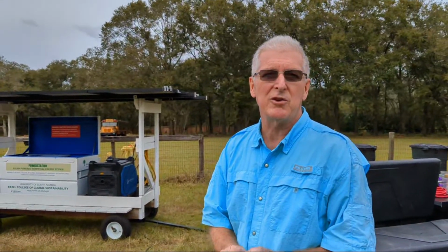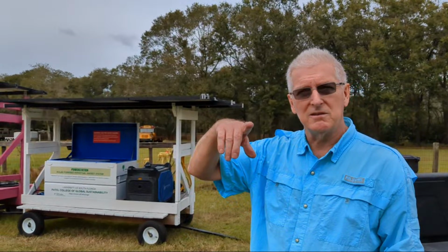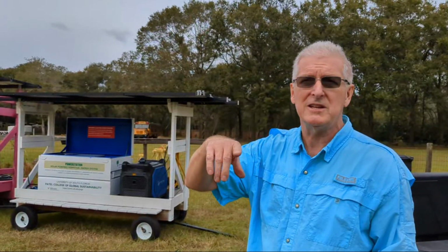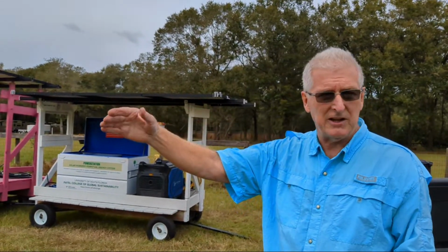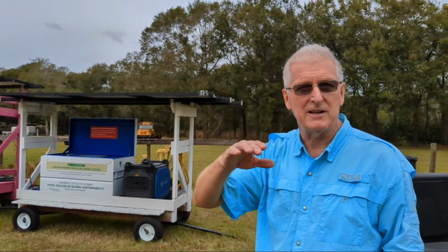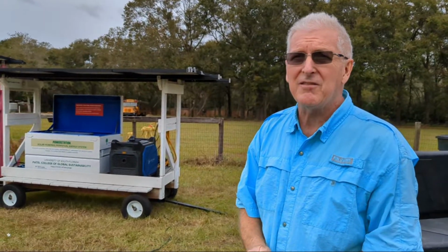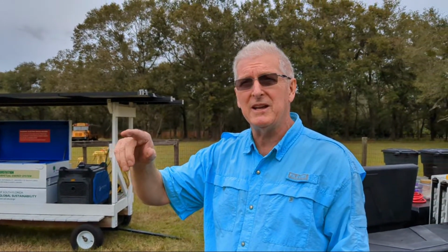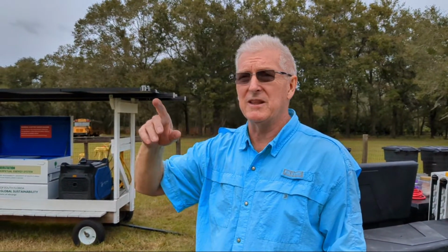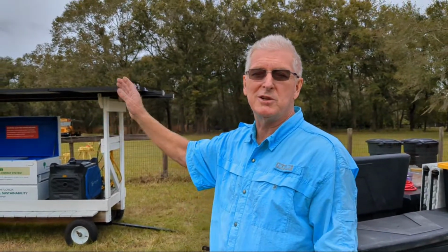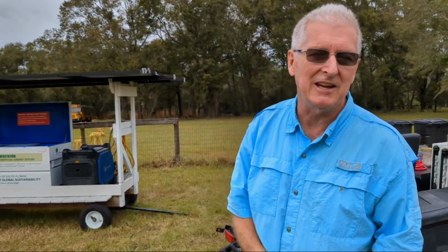This is a grid-tied inverter that meets the code called UL 1741, which means it's listed for bi-directional energy flow, so you get a credit when you're connected. The Victron Energy system does not have the UL listings that would permit it to export power to the grid. And if we had used a system like that, we would have lost the capacity to have this function in the way that we need it to function.